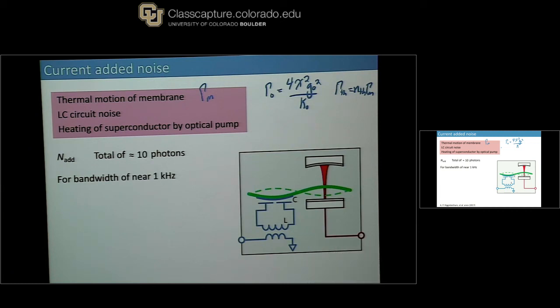One of the things that we're suspecting at the moment is that when we put the niobium thin film down, there's some sort of oxides on the surface that could be noisy, and we might try to switch to niobium nitride. That would be a better material.